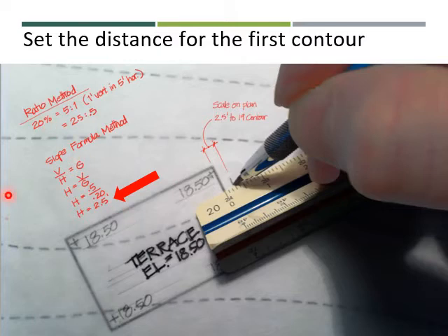We will not be going up a full foot here, only 1/2 a foot. Now, because you know from the previous slides that if you were to go up or down a full foot, you'd be going horizontally 5 feet. And of course, you can also do the math and determine the exact same thing. The horizontal distance we're going to be looking for away from the corners is going to be 1/2 of 5, or otherwise